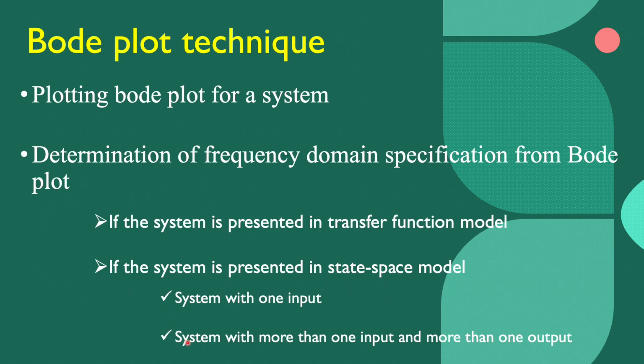In this section, plotting of the Bode plot in MATLAB and determination of frequency domain specifications from the Bode plot in MATLAB are discussed. Here you can see the plotting of a Bode plot for a system. Next we try to find the frequency domain specifications from the Bode plot in the MATLAB environment.